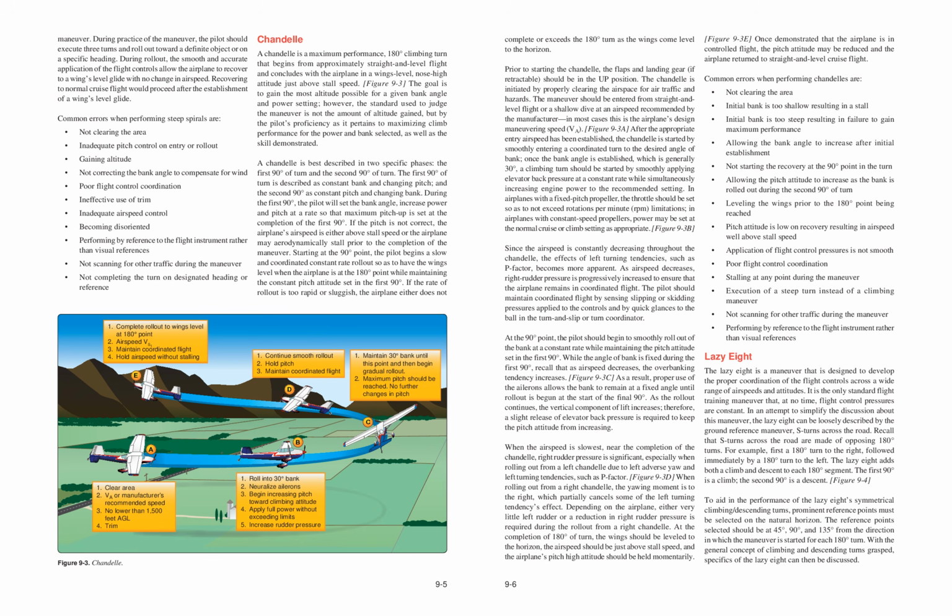Application of flight control pressures is not smooth. Poor flight control coordination. Stalling at any point during the maneuver. Execution of a steep turn instead of a climbing maneuver. Not scanning for other traffic during the maneuver. Performing by reference to the flight instruments rather than visual references.